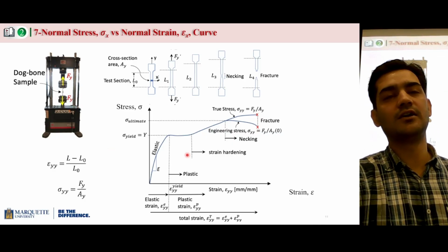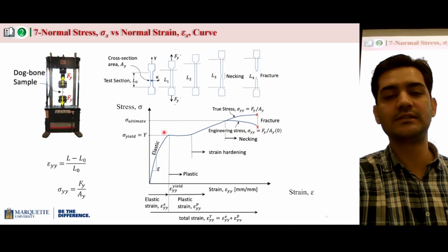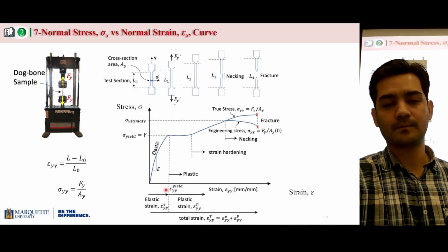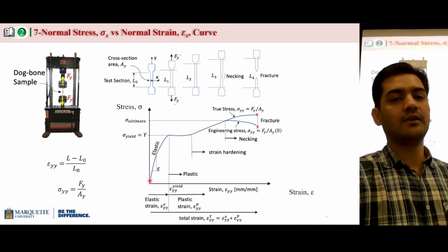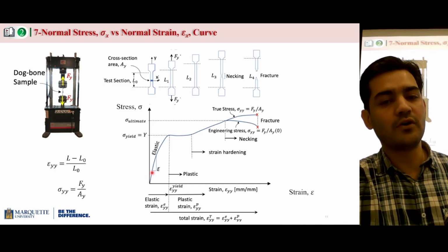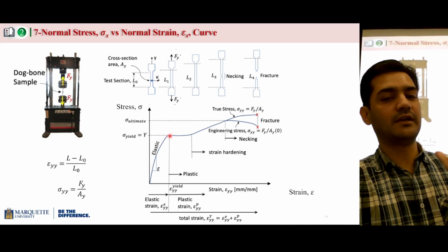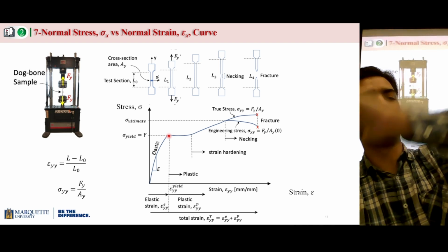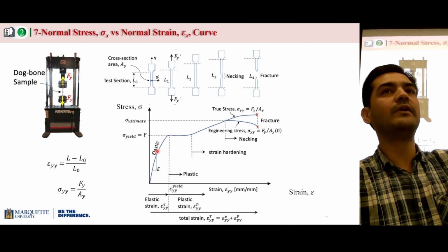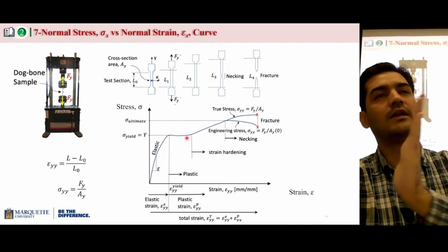And this stress strain curve is specific for all the materials. Like for any material, this is specific. So this stress strain curve is for a specific material, let's just say steel. So you can see when you keep on increasing the forces, you're gonna keep on increasing stresses and strain, but in the elastic region. So in the elastic region, the stresses are directly proportional to strain. So if you keep on increasing the force, you're gonna keep on getting increased stresses and strains, but till a particular point. And then after that, you're gonna see a plateau.